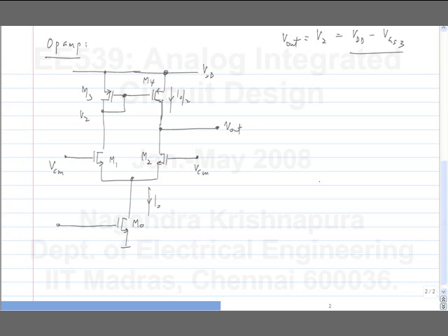Now, I can think of this as a transconductor or a voltage amplifier. I can open circuit the output and think of it as a voltage amplifier, or I can short circuit the output, measure the current, then I am treating it as a transconductance. When I want to measure the parameters of the transconductance, I need to terminate the output in an incremental short circuit. Okay, when I want to measure the output current of the transconductor. What will I connect in the large signal picture?